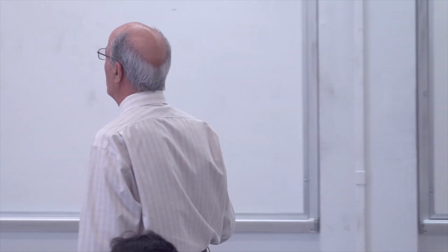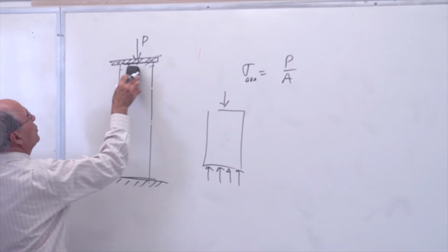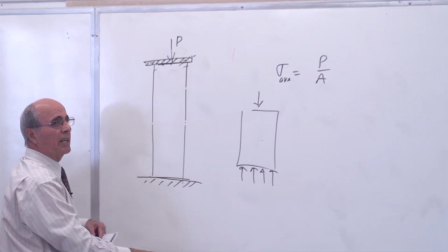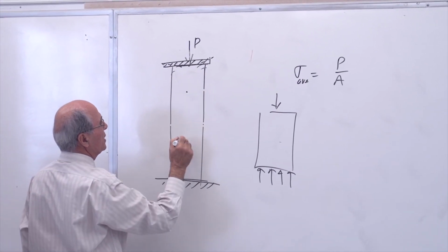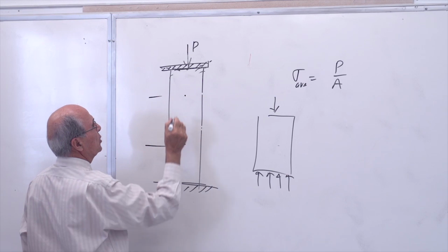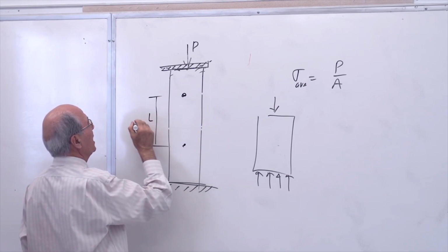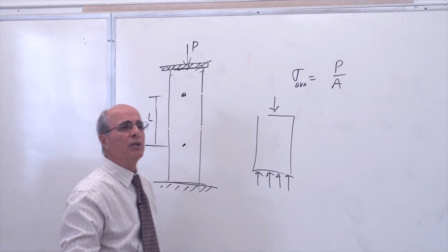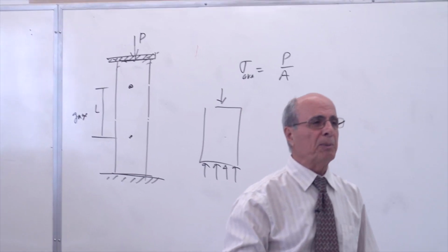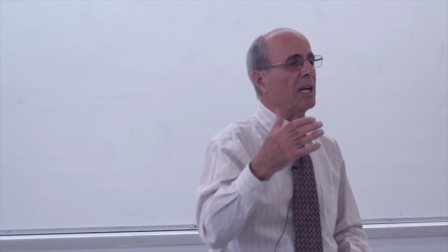So therefore, in typical testing scenario, which you have to grab here, and pull this, you don't go to this here. So you go to 1/2 at the middle. So that you put 2 spots here. And if this is the L, we call this L, we call it gauge length. Gauge length is where the stress become uniformly distributed, because near the end you are grabbing there, so you have a stress concentration, so you have to get away from that point.